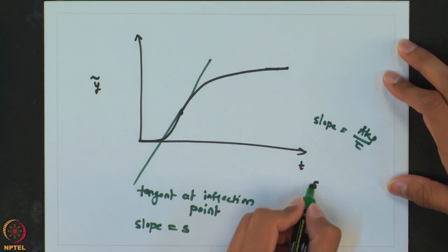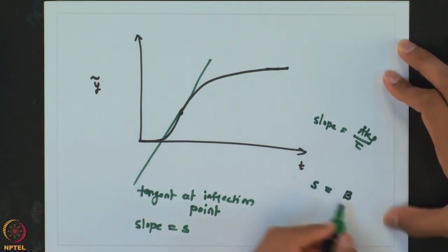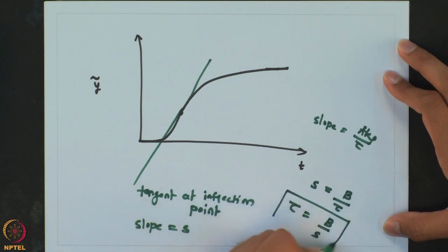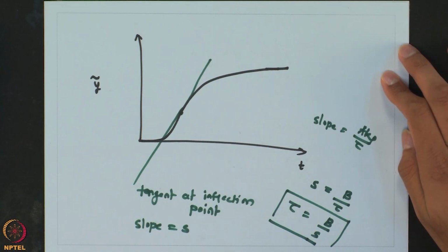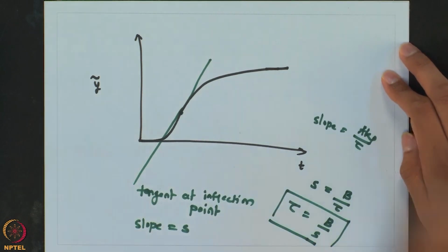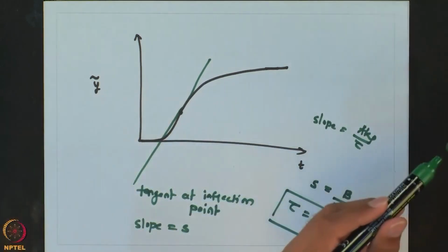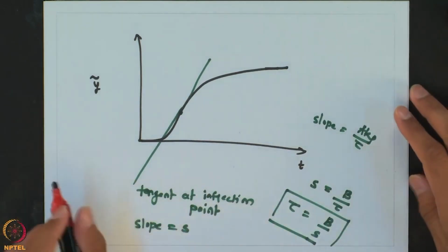In this case, the slope is s and A Kp is nothing but b. So b over tau, and we'll write tau as b over s. So the tau value which we are interested in is equal to the ultimate value of output y divided by the slope of this tangent at the inflection point. And then lastly, the only thing remaining is the dead time.